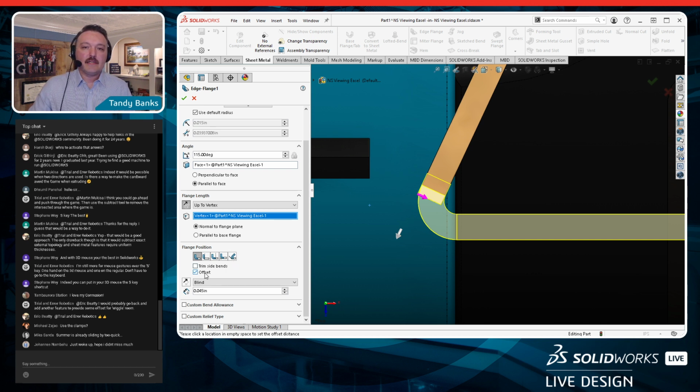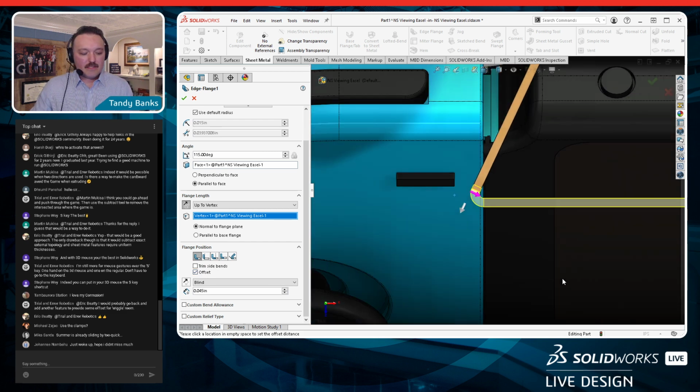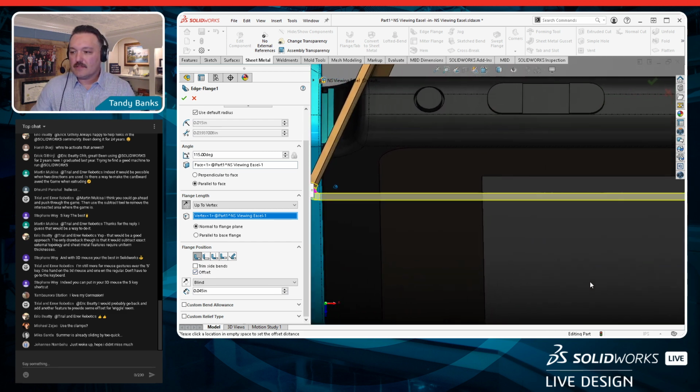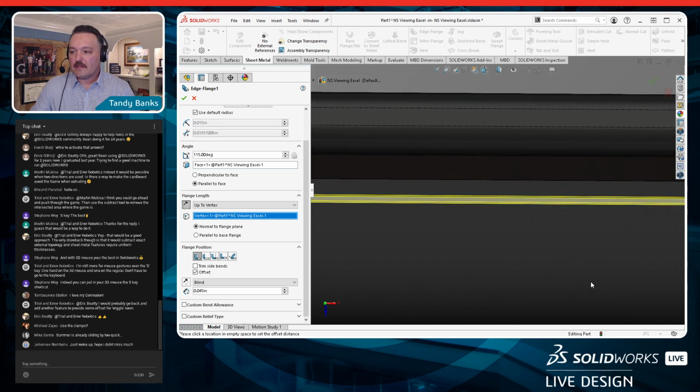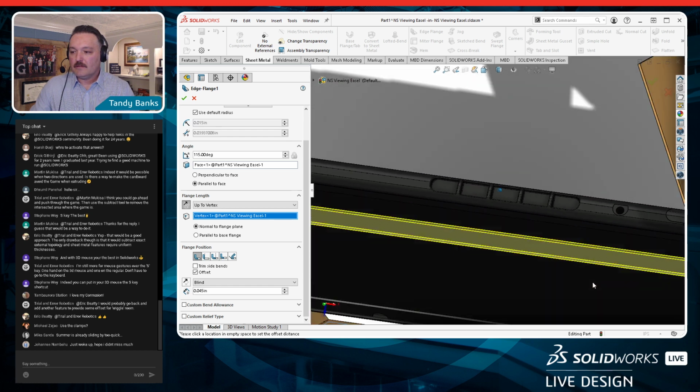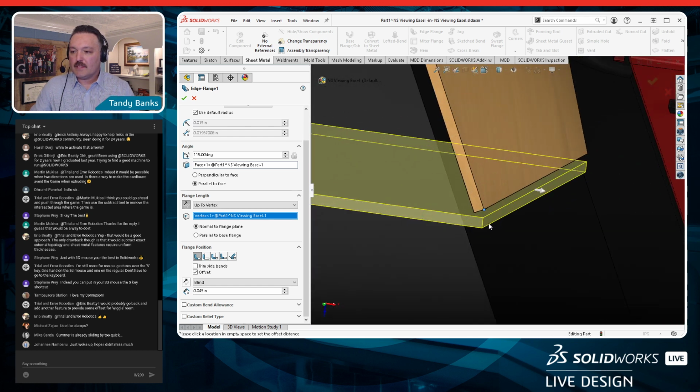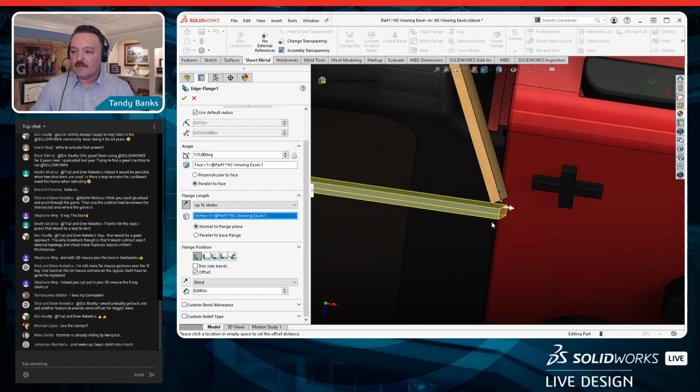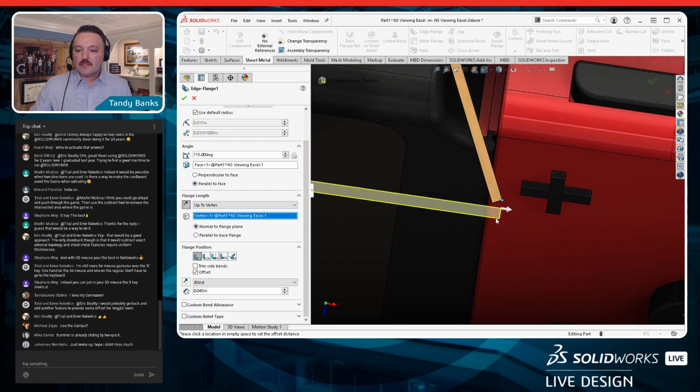And then we've also got, in combination, this offset ability, where I really want it to be within my original geometry, but I've got to worry about this other end. So let's zoom out here and look at this other end. We'll see that I want to make sure that I've got a little bit of a gap in here. I'm using 45 thousandths, 0.045 inches, as a gap to make sure that I'm maintaining a little bit. I'm working with cardboard here.